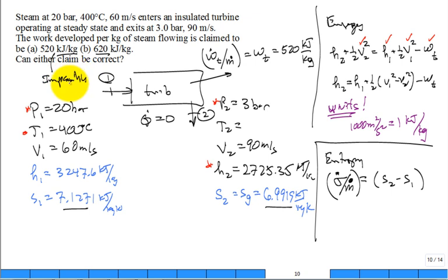You say that it violates the second law of thermodynamics, because to be possible, it would have to destroy entropy, and that's impossible. Sigma dot per m dot is calculated to be negative 0.135 or something kilojoules per kilogram Kelvin. Oh boy, I got to work those out. Yeah, I think that's right. Yeah, that's it. All right.